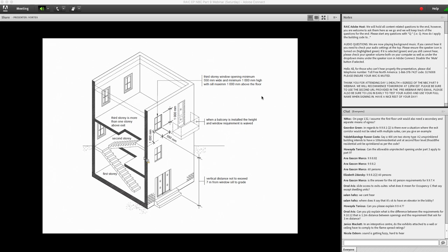And the intent is that, if for some reason the access to the exterior exit doorway on the main level is compromised, then they can have a temporary area of refuge provided by the balcony, to enable, for instance, firefighters to get them off the building.